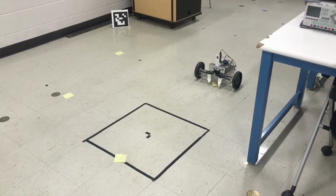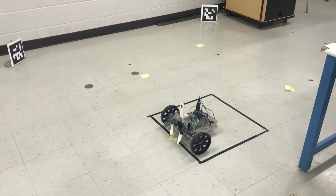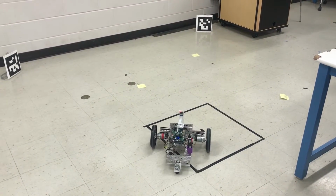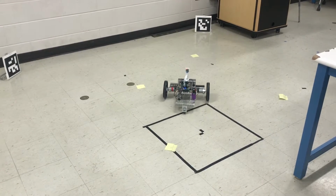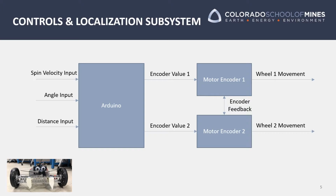A feedback controller was implemented to control the movement of the robot in one of 3 possible movement states. Spin velocity control, which took in a set point as the speed in radians per second that the robot should spin, angle control, which turned the robot a specified angle, and distance control, which drove the robot in a straight line until the distance was reached.